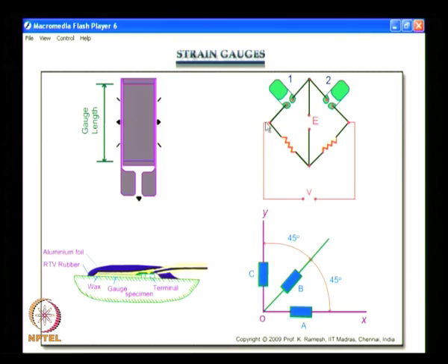Here I have a Wheatstone bridge shown, and this also has two strain gauges connected, in a half bridge configuration. In fact, this is the most celebrated one because it also has temperature compensation provided, when these two strain gauges are representing the point on the model of interest and the one which is also kept at the same temperature, so that any temperature effect happening at the specimen is compensated by the second strain gauge.